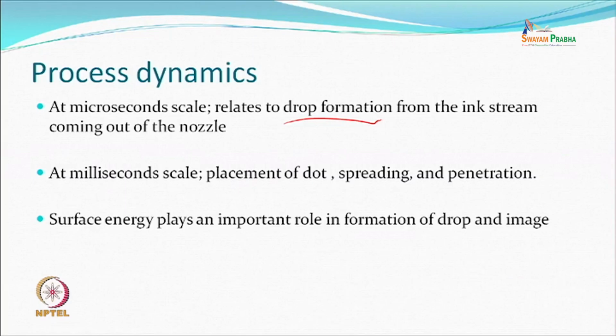The surface energy of the solution itself, which is related to surface tension, can be changed by adding surface active agents or any other solvent. Like when you dilute something, viscosity changes, we understand, but if you add another solvent instead of the same solvent, then the energy also changes other than the viscosity.